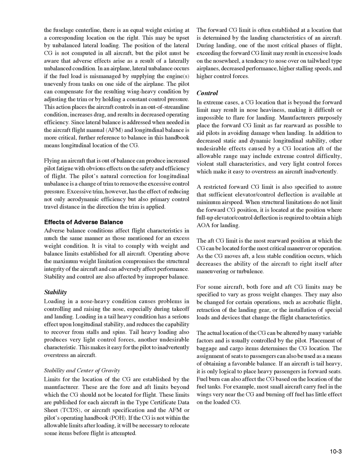Since lateral balance is addressed when needed in the Aircraft Flight Manual, AFM, and longitudinal balance is more critical, further reference to balance in this handbook means longitudinal location of the CG. Flying an aircraft that is out of balance can produce increased pilot fatigue with obvious effects on the safety and efficiency of flight. The pilot's natural correction for longitudinal unbalance is a change of trim to remove the excessive control pressure. Excessive trim, however, has the effect of reducing not only aerodynamic efficiency but also primary control travel distance in the direction the trim is applied.